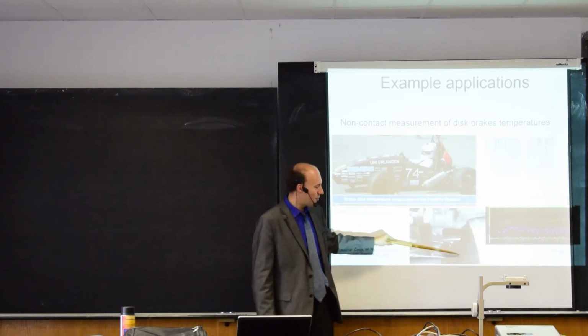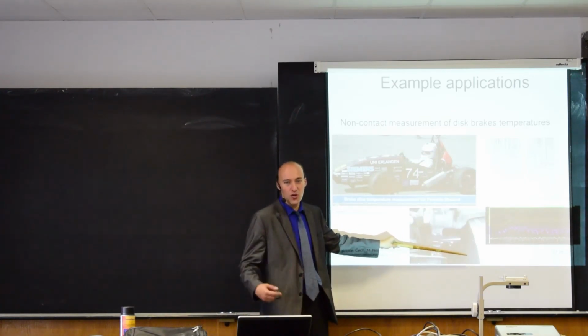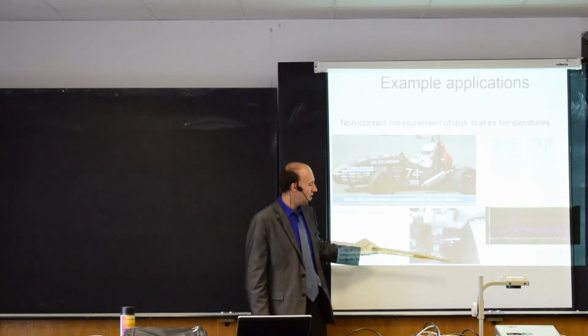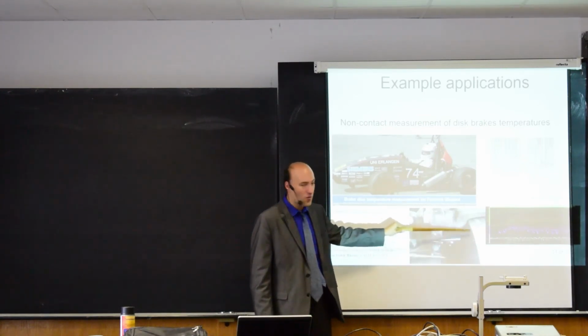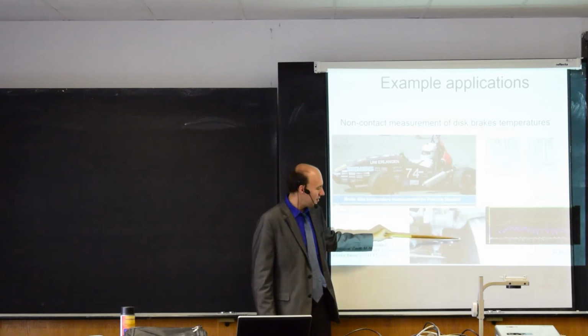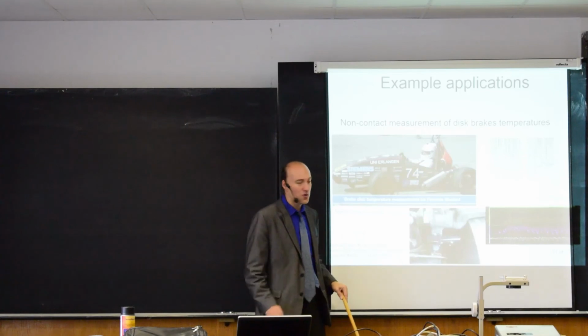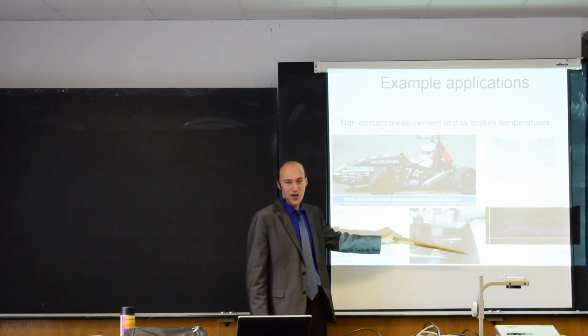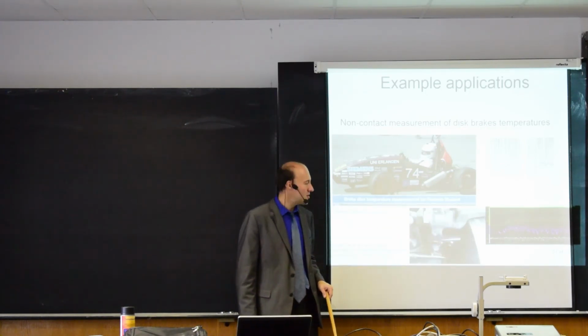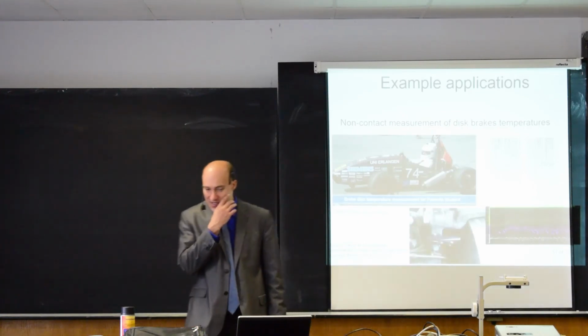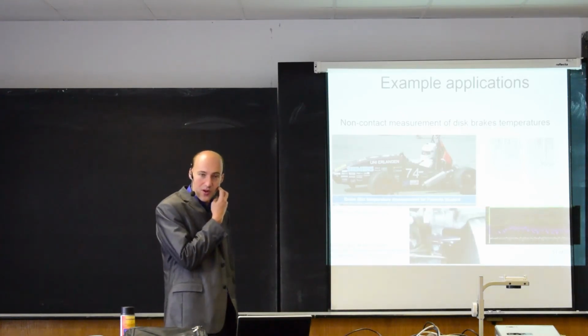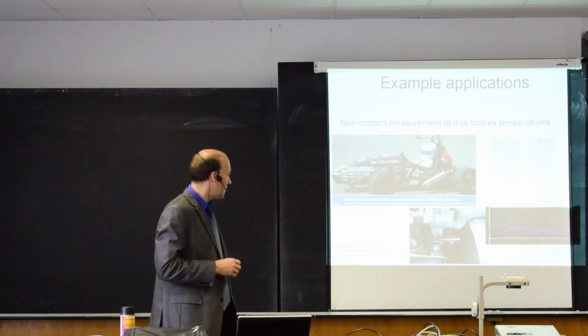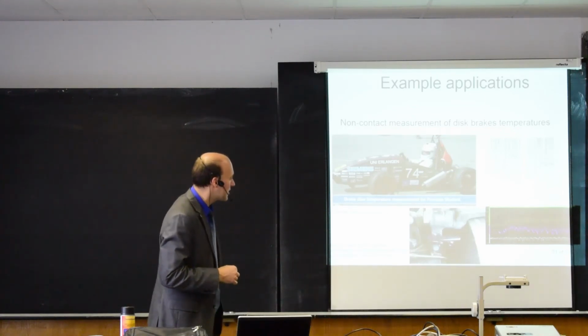So they were spraying water directly on the disc to cool it faster down, and at this moment there was water vapor all around it, and in those 3 centimeters distance, the radiation was completely blocked by the water vapor. So this was working fine until they started spraying water on the disc to cool it down. So all this needs to be taken into consideration when you measure without contact the readings.